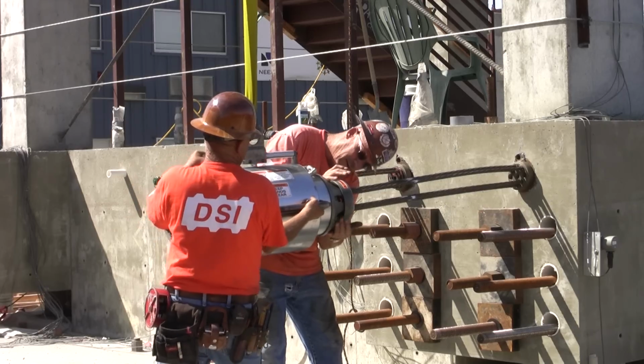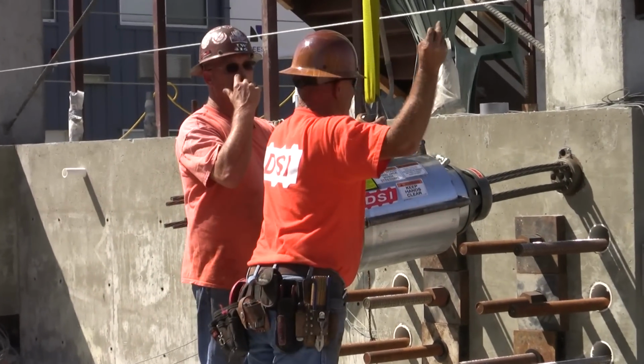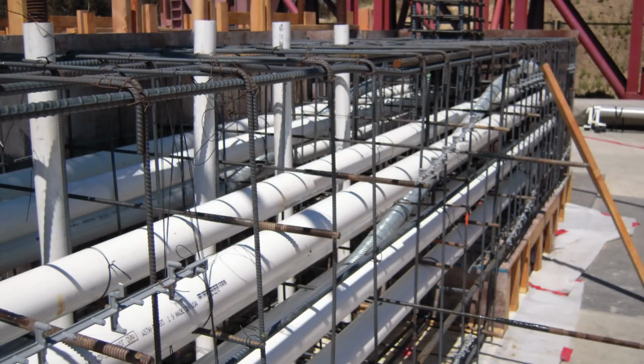In bonded post-tensioning, grout is poured into the void after the tendon has been stressed to its desired level, creating a bond between the steel and the concrete, and allowing the reinforced concrete to reach a higher overall strength. In this particular project, high-strength rods and tendons were placed inside ducts made from PVC pipes, which were cast within the foundation. The rods were left unbonded and tensioned after placement, while the tendons are bonded with the grout.